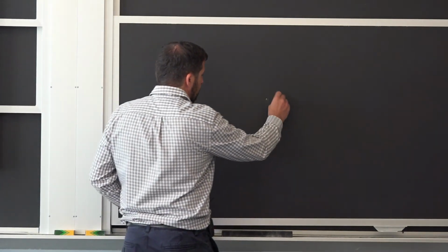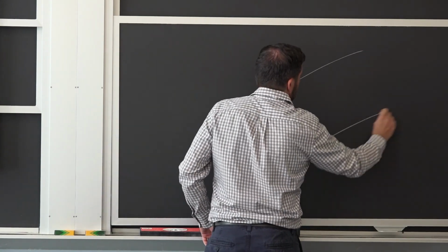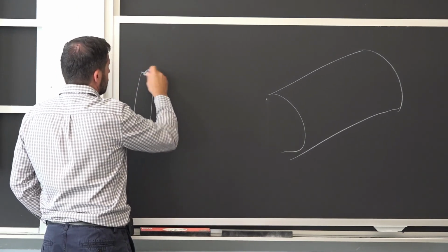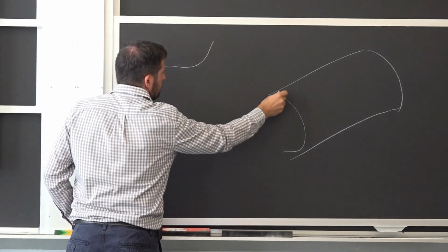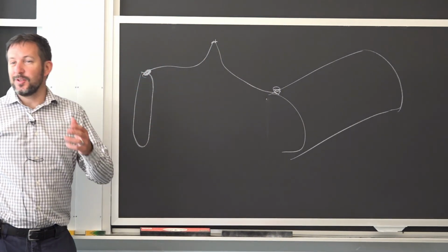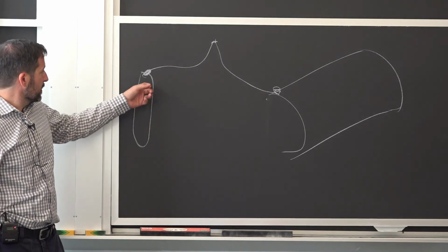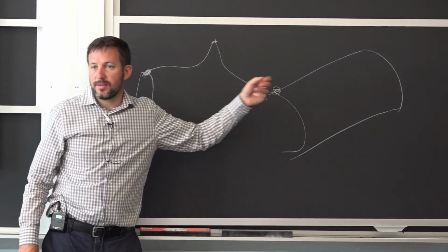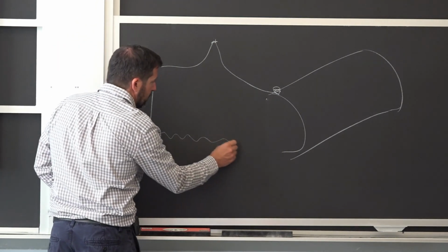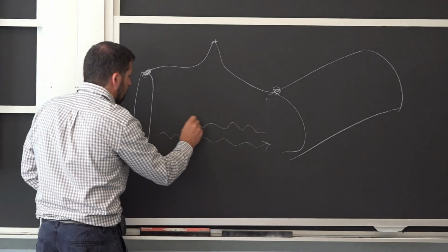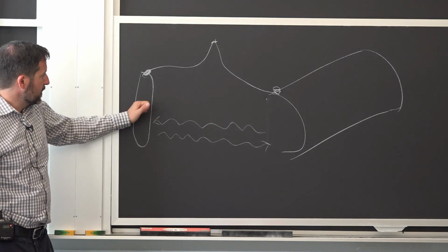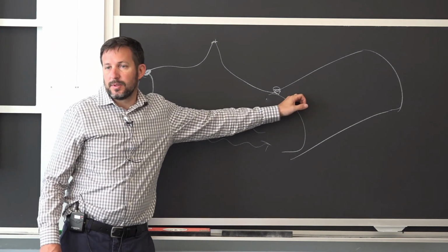I'm going to draw it off. So we have the pipe here, and then we've put on an anode right here. We put this little weld that I've shown. It goes to the access port. I connect the two wires. So this is essentially creating a galvanic effect. So physically, this and this is touching electrically. Now I have my ions that are going to be going through the soil from one path to the other. That's how I established that this is going to corrode instead of this one.